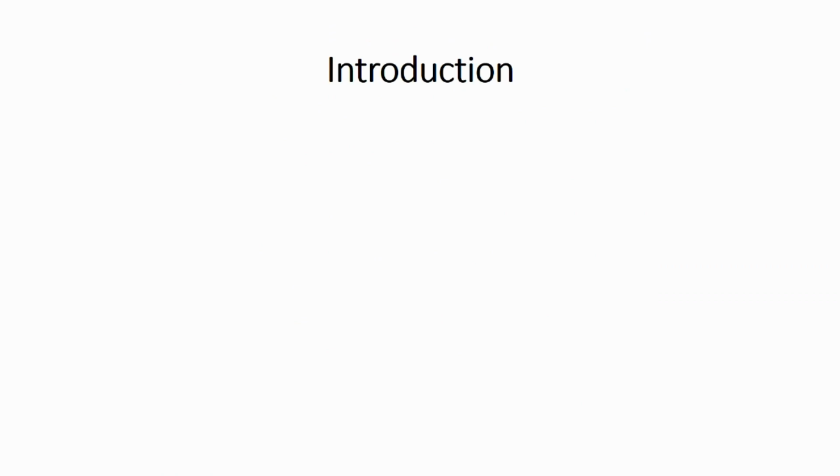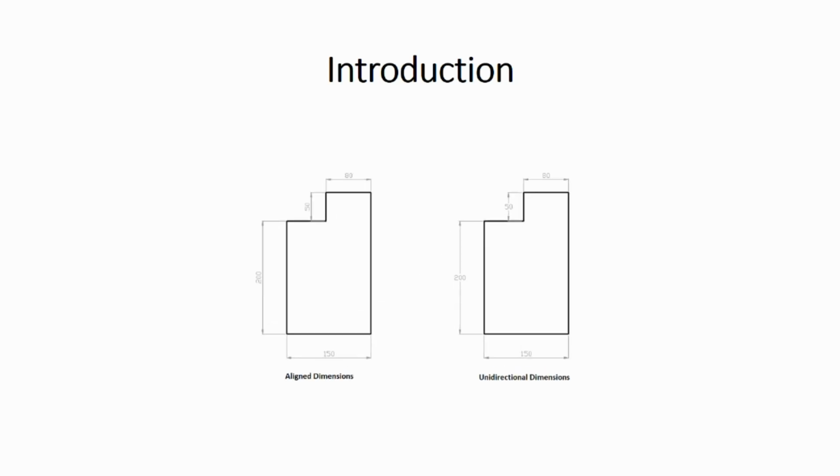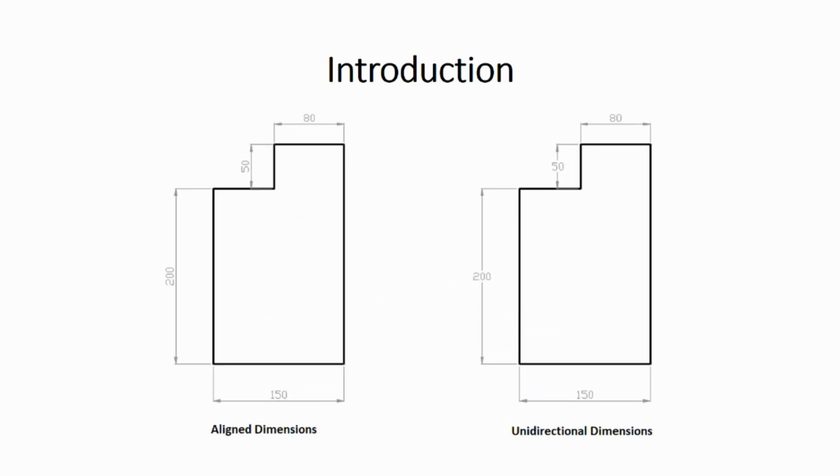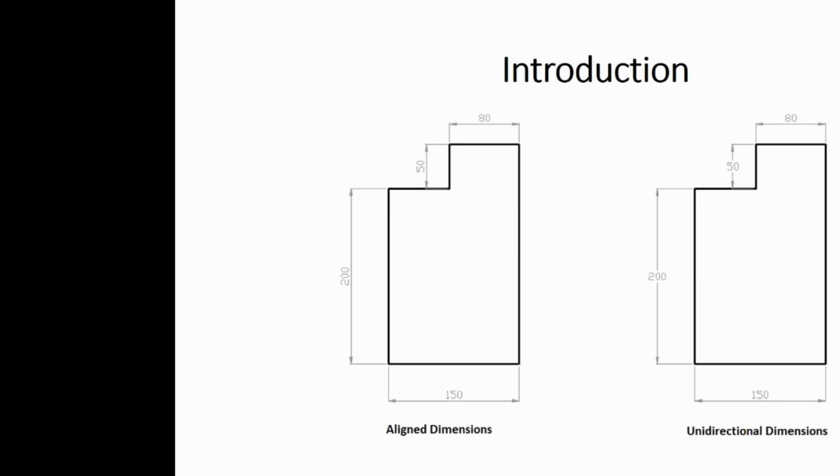In engineering drawing, there are two systems of placing dimensions. One is termed as the aligned system, and the other is called the unidirectional system. In aligned system, the dimension is placed perpendicular to the dimension line in such a way that it may be read from the bottom or the right-hand edge of the drawing sheet. The dimension should be placed near the middle and above, but clear of the dimension line. On the other hand, in unidirectional system, dimensions are so placed that the whole dimension is written in the same direction in the entire drawing, and this direction is generally vertical.